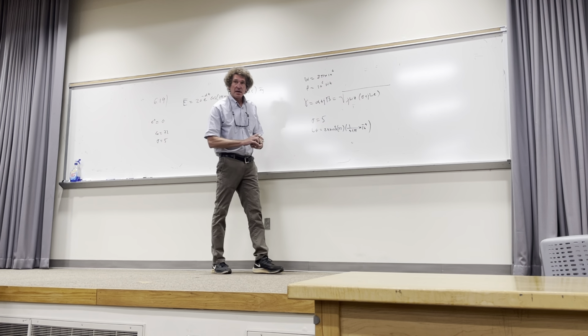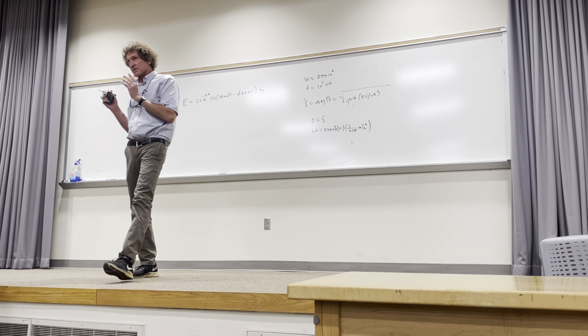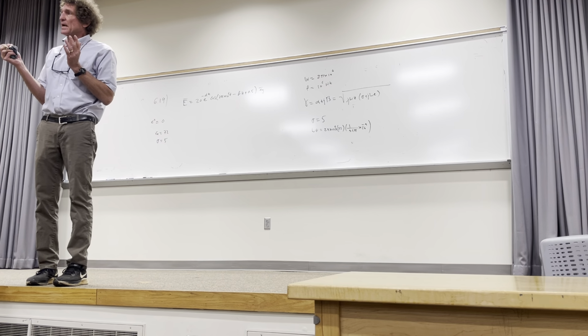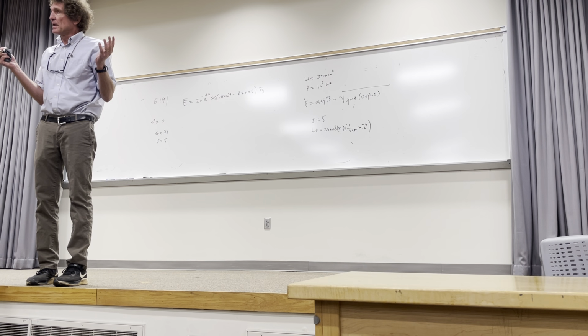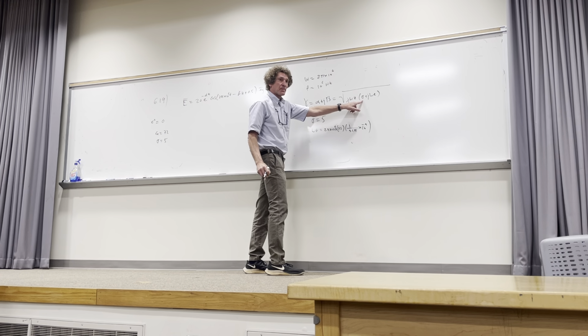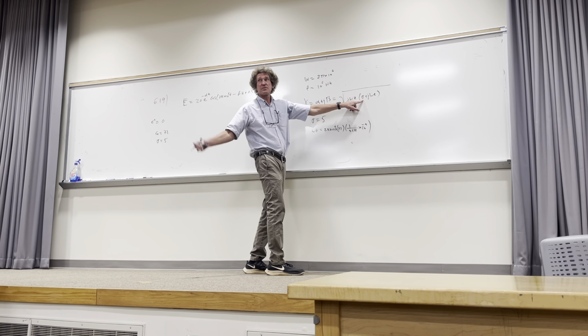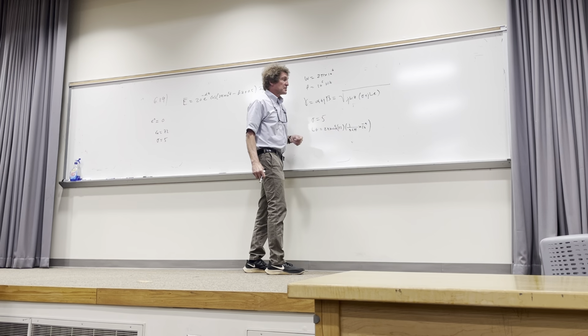Now the only thing I'm doing here is getting this term and this term separately, and I'm going to contrast them. If sigma is much, much bigger than omega epsilon, I can ignore omega epsilon. You all follow me? Everybody? If you take a look at this, I've got sigma here, and right next to it is omega epsilon. Well, if sigma is orders of magnitude larger than omega epsilon, I'll ignore omega epsilon, right? That j doesn't do beans as far as anything, it's a phase term. Then if I do that, what I can do is get a simple approximation.